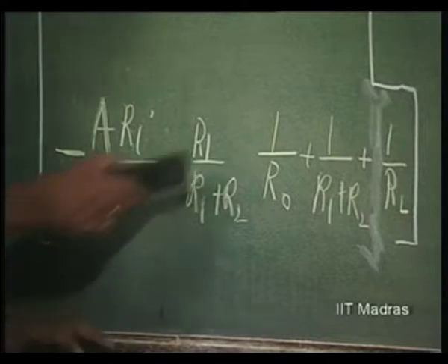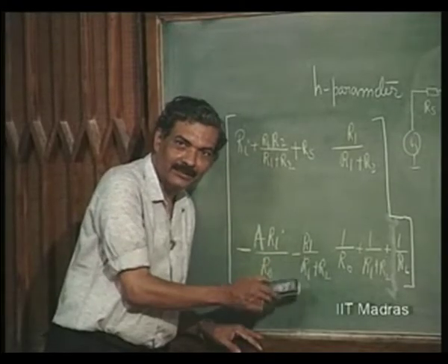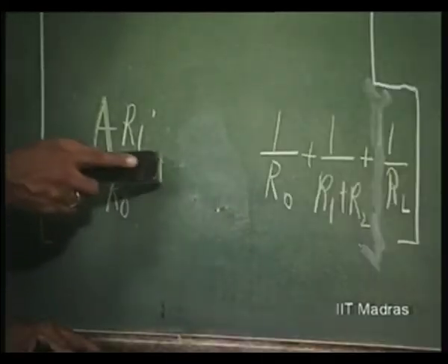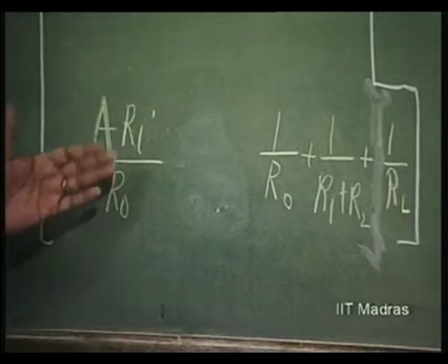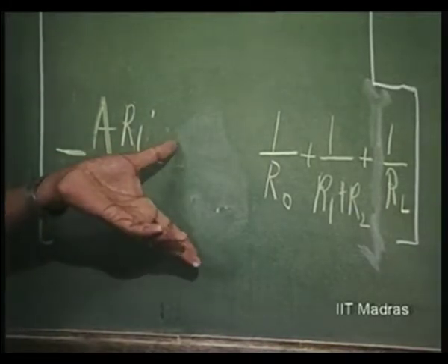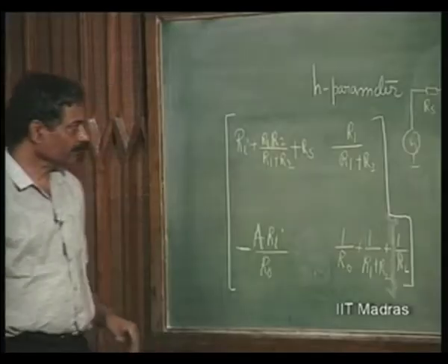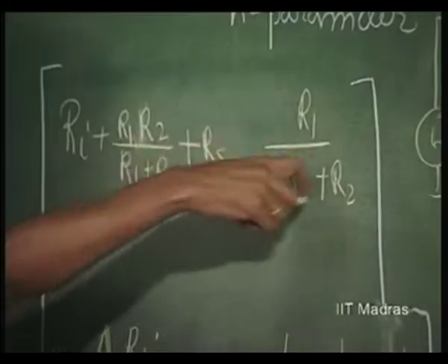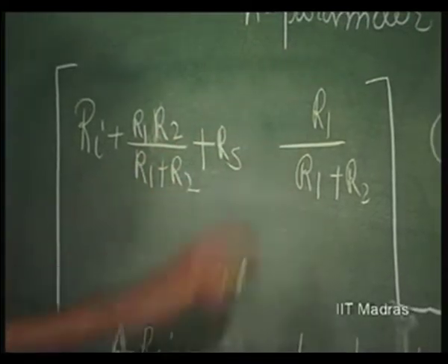So, there is no point in retaining this, which is always a fraction. So, this can be ignored compared to this always. That means the forward transfer parameter contribution due to passive device can be ignored. Here the active device has not contributed to any reverse transmission at all, that is something that you have to remember. Only the passive device has contributed to the reverse transmission.